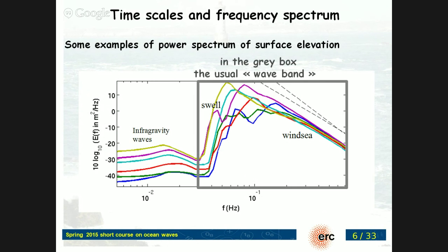And that's a typical wave spectrum. What we use to model is only this gray box here, essentially starting from a wave period of about 30 seconds, so 0.03 hertz, that's 30 millihertz if you want. This is 0.1 hertz, so that's a 10-second wave. That's a typical peak period in the Pacific, for example. And as you go to higher frequencies, you see the energy is going down. So this is a log scale of the spectral density, all right?